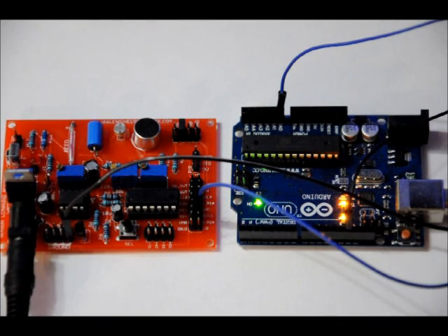So let's have a look at those numbers. Sorry if you can't see that too well. I believe it's a 10-bit analog to digital converter that the Arduino has on A0. I might be incorrect. So this is just normal lighting. We see a value of about 243 roughly. And those will change a little bit based on line noise and whatnot. If I just cover the sensor with my hand to offer a little bit of darkness, it goes up to 400.